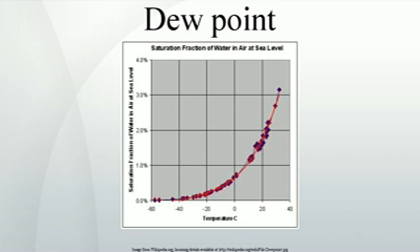The more complete formulation and origin of this approximation involves the interrelated saturated water vapor pressure, in units of millibar, which is also hectopascal, at T, PS,T, and the actual water vapor pressure, also in units of millibar, PA,T, which can be either found with RH or approximated with the barometric pressure in millibar units, BPMB, and wet bulb temperature, TW.